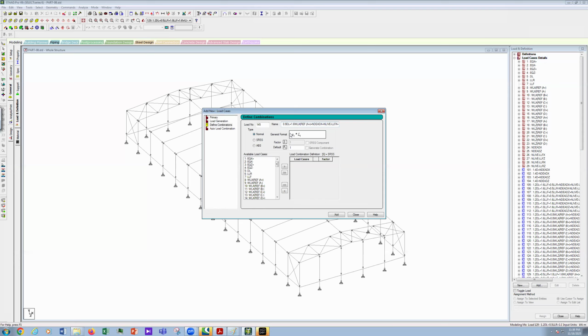So we don't have any roof and floor notional load. Only notional load for dead. So we don't have any notional load for floor live load or roof live load, because the original load combination doesn't have any floor or roof live load. So this is our case.